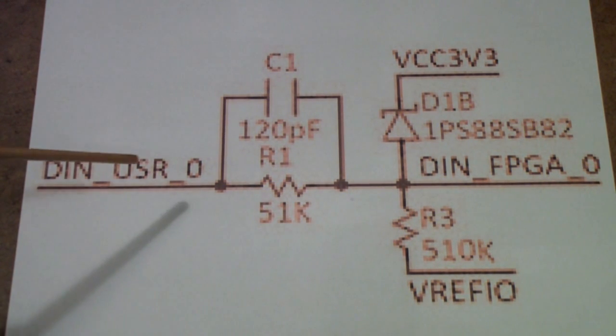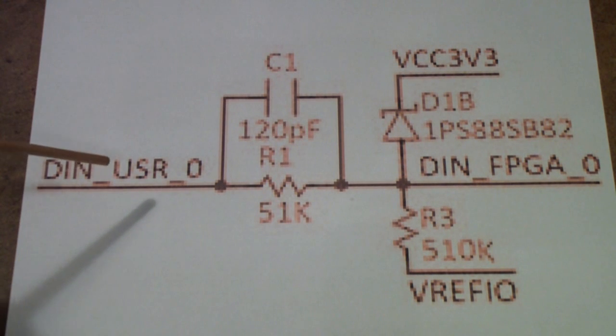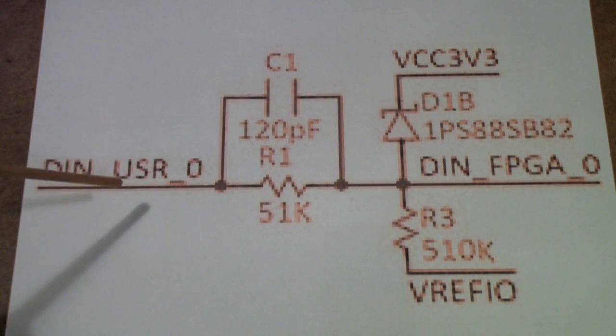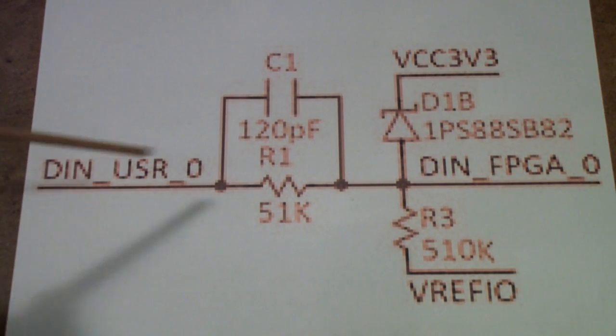The reason I point that out is, of course, don't try to use this in a 12 volt logic circuit, for example, or anything like that. It's just not made for that. It's made for, at most, 5 volts input. And frankly, it's optimized for the low voltage CMOS, in other words, 3.3 volts and below.